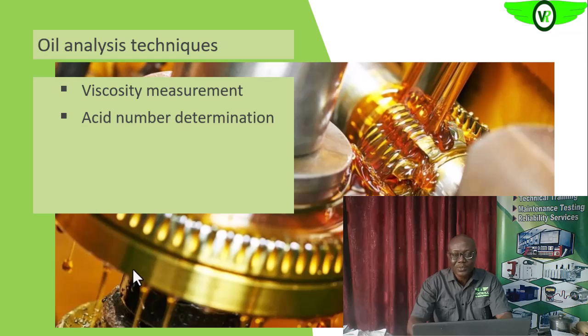Then we also look at the acid number. That's to determine if the oxidation also increases the acid number of the oil. We know that the more acidic the oil is becoming, the more corrosive it will be. So it gives us an indication of the fitness of the oil in our equipment.